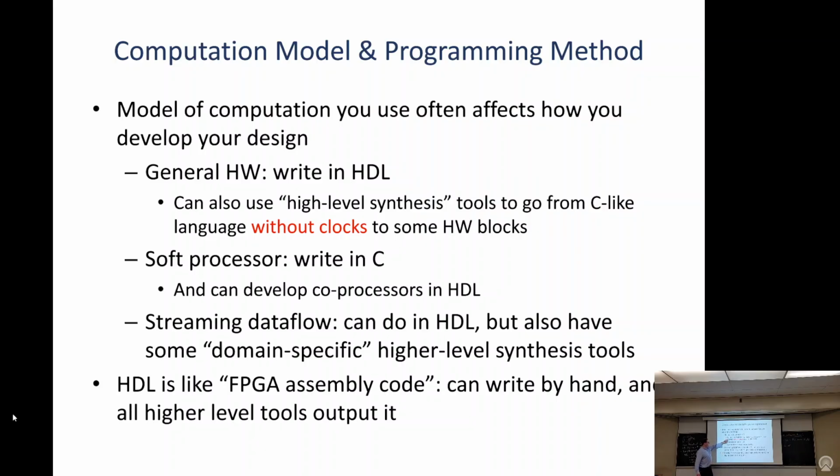So what's high-level synthesis? It goes from a language, usually C-like. There's no standard, but it's usually C with some extra constructs. And the key distinction between HDL and high-level synthesis is you don't have clocks, right? In HDL, you've decided where your clocks are. You know whether you pipelined or not, et cetera. In high-level synthesis, you don't know that anymore. You might give the tool hints, but it's up to it to decide where the clocks are. So that could be a productivity advantage, but it's usually come with a performance penalty so far. But there's lots of people working on that.